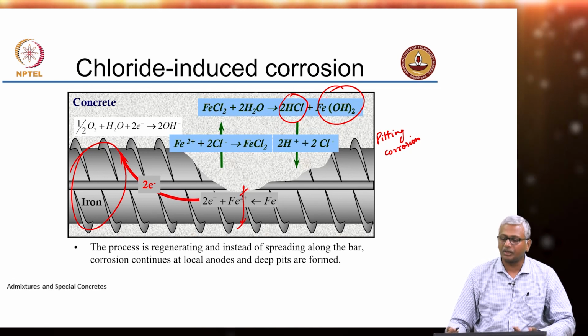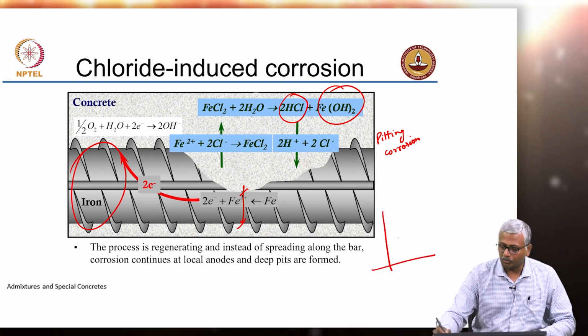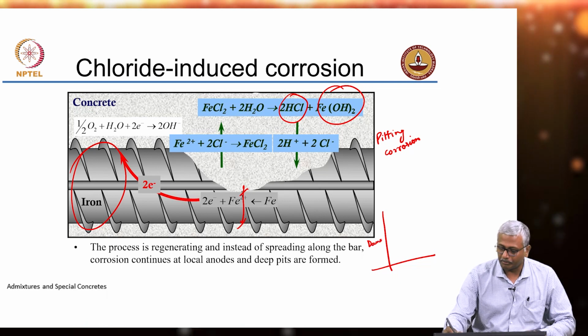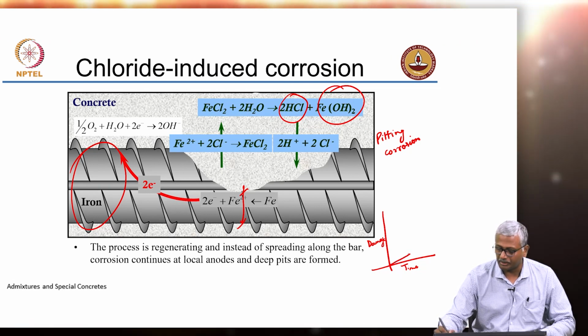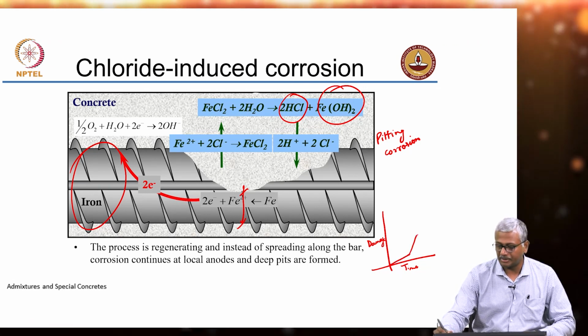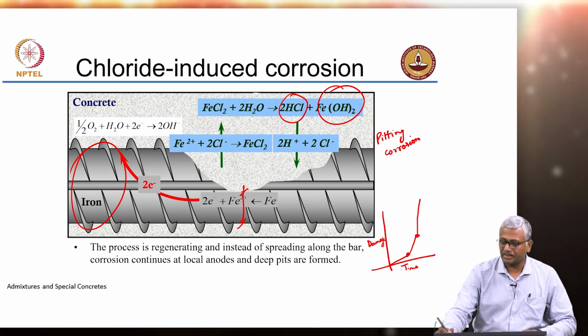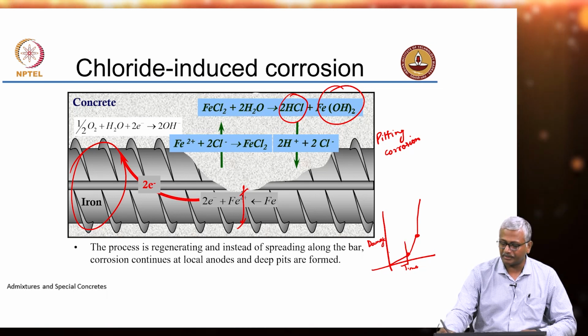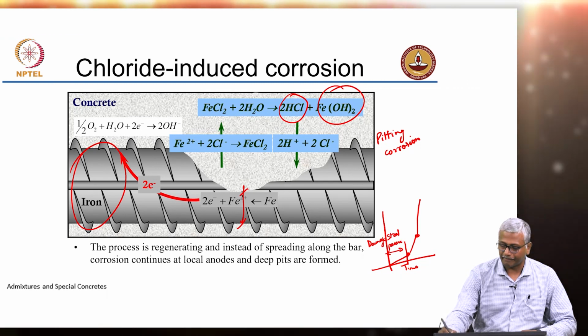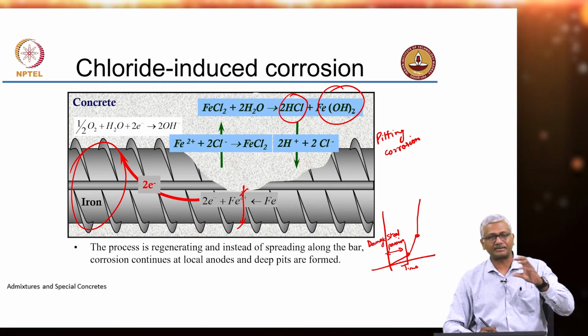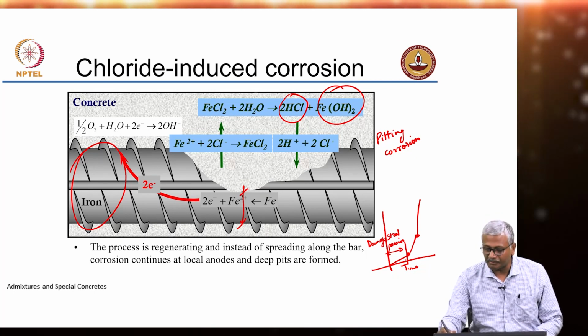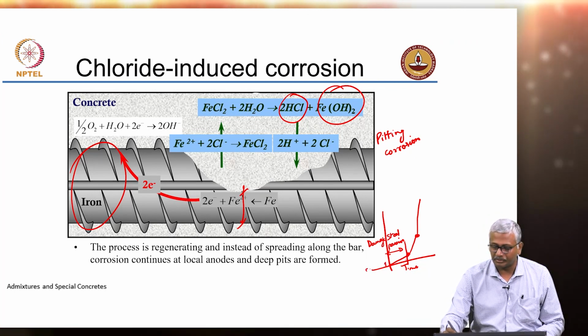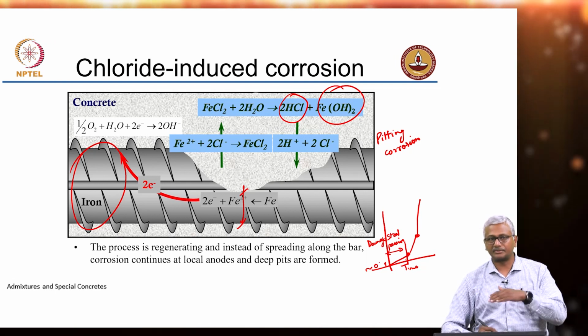So, if you typically look at the damage due to corrosion and you plot that with respect to time, you will see this kind of a relationship. Initially there is very little damage, then there is suddenly high damage, and finally very high damage. So, there are three essential zones. This is the zone where the steel is mostly passivated. That is because the film is intact in that zone. While I have put some damage here, actually there is close to 0 damage in that zone.